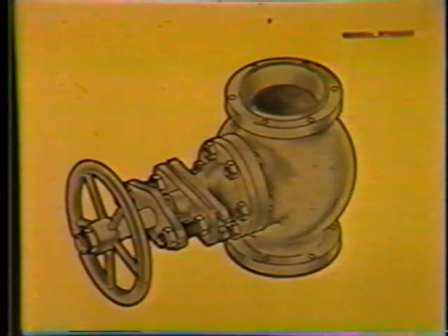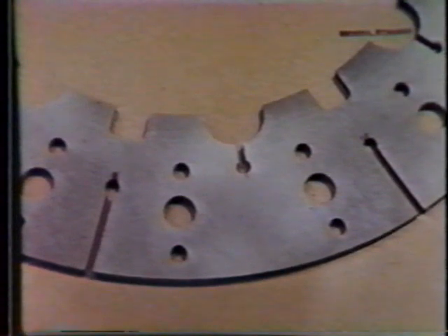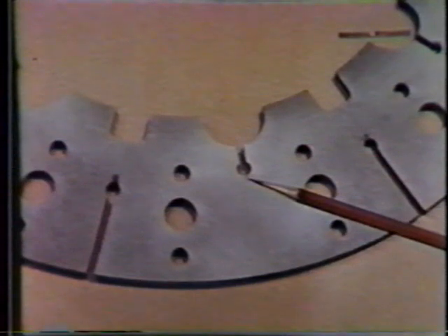Coarse surface defects in a rough casting, or fine cracks in some exotic material, such as the boron aluminum tubing in a space vehicle. Color contrast and fluorescent penetrants have about the same penetration ability. Either may be used in locating large discontinuities. The primary limitation of color contrast penetrants is getting enough contrast, enough penetrant into a discontinuity to form an indication. To gain contrast, a heavy concentration of dye is used, plus developers that provide a flat white background.